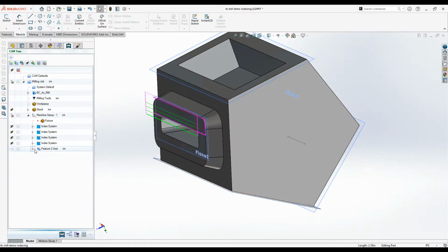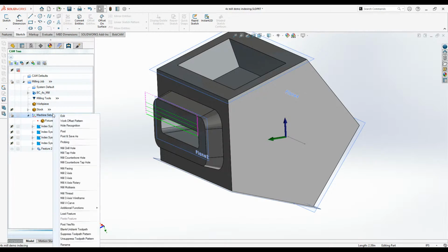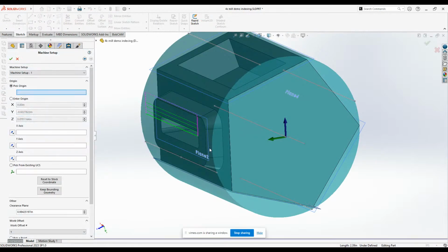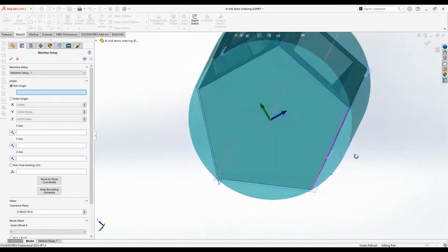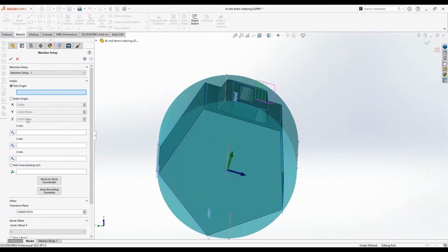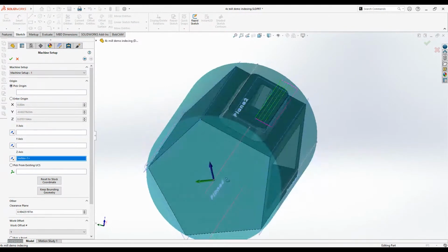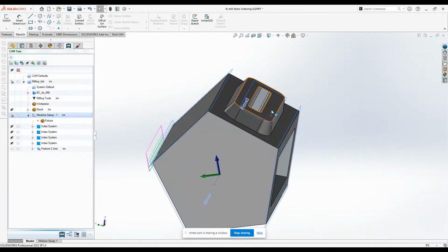But yeah, I mean, if we were using the machine setup as what it was before, and we're doing many milling operations, then indexing to this location, say we've got our z-axis to what it was here, we'll change the z-axis pointed to this location, and then we're indexing across to, and then we're indexing at that location later on.